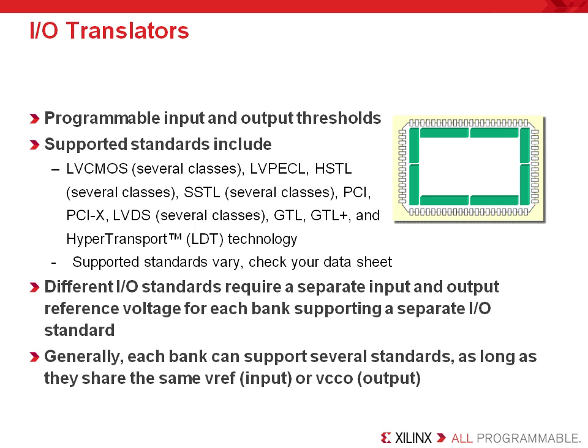Generally, designers put just one I/O standard within a single bank. However, each bank can support several different I/O standards in the same bank, as long as they share the same reference voltages. So designers have to take the time to verify that their I/O standards are compatible. To do this, check the necessary required voltages for your I/O standards from the device datasheet.